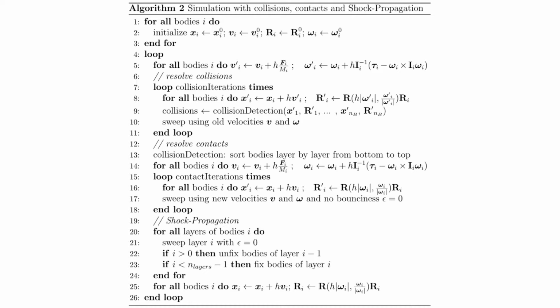Now, this will not be part of the homework, but let me maybe anyway mention how this can be dealt with. So this was the method we had in the last lecture. And now, instead of resolving all these joints one by one, there is a way to resolve them globally, meaning that you can basically update all these bodies at once, and then measure all the constraint violations at the same time for this new state, and put them in one big vector D that contains all these constraint violations. And then also one needs to construct a global matrix that accounts for all these joints at the same time.